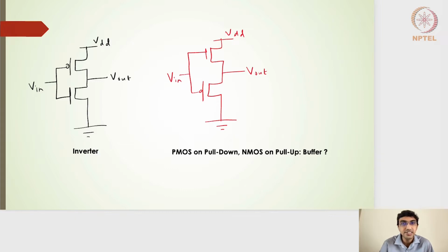This particular region is our inverter, and this one is the new design which we are talking about. So let me pick up a pointer and start emphasizing the different points. This is our inverter design, which we had seen. We know that the PMOS transistor and the NMOS transistor are connected in series, and thereby we were able to visualize the V output steady state voltage for a given steady state input voltage.